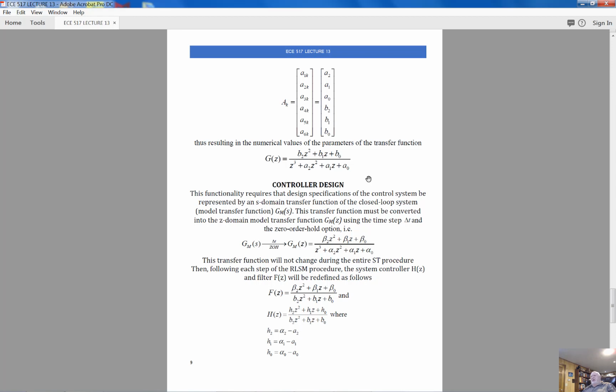What is good about it? What is good about it is this. This coefficient may represent friction in the bearings. This coefficient could be affected by the stiffness of some springs, for example, stiffness of the oil spring in the flight actuator. And the stiffness of the oil spring will change if there would be water contamination or air contamination. So you see, some of these parameters will be changing drastically if there is battlefield damage inflicted on an aircraft.